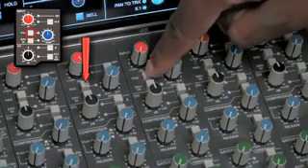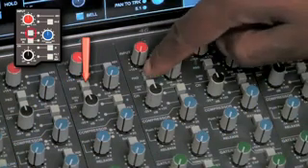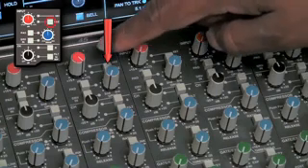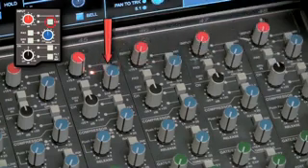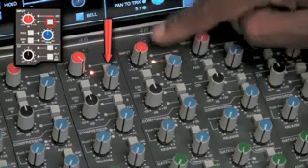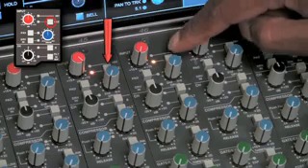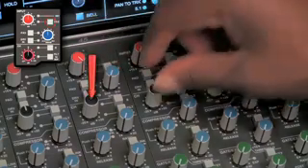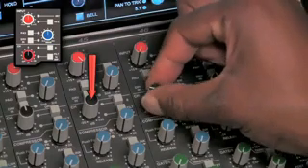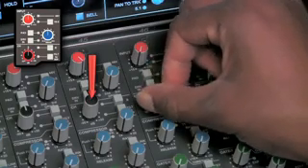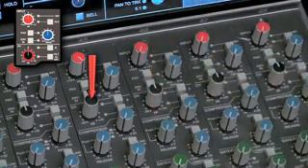Next is the 24 dB pad and a high impedance switch useful for DI in guitars and bass. Next is the channel trim pot. This gives you plus or minus 20 dB of gain control. This allows additional gain control before the rest of the channel's processing.